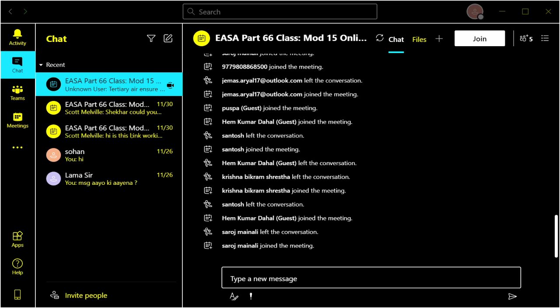At the top of the tank inside, you'll have what's called a deaerator tray. And as it sounds, it gets rid of the air in the oil as well. So the oil will be splashing around, and the air mixture will go in this deaerator tray. You can just about see it, maybe hard to see here, there are very, very fine holes. The oil will drip through the holes eventually, and the air will float up, and then that will go out through a vent valve in the tank.